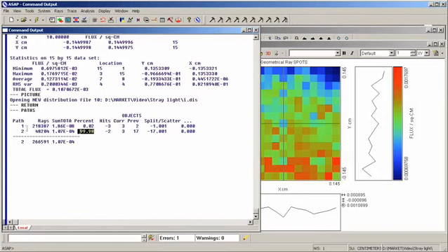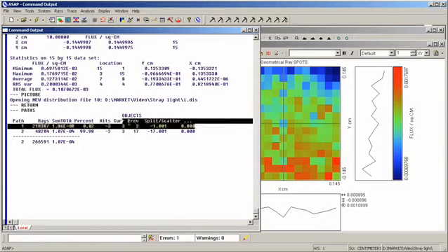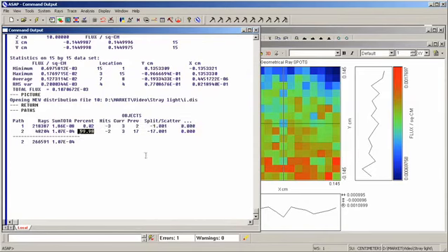So looking at this table, we see that the light scattered from the inner conical baffle, which has over 99% of the stray light, is the most important path, and that the primary mirror contributes only 0.02% of the total stray light. So if we have a stray light problem, it does no good whatsoever to correct the primary mirror. We have to direct our attention to the inner conical baffle. Otherwise, the stray light will simply not be affected to any significant degree.